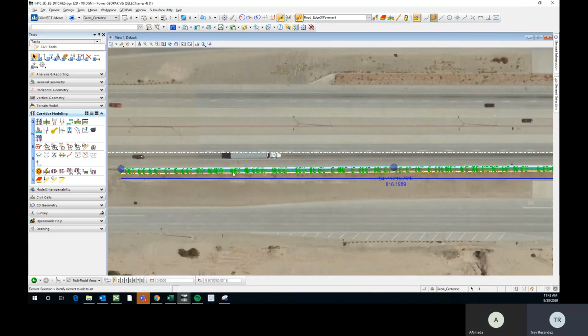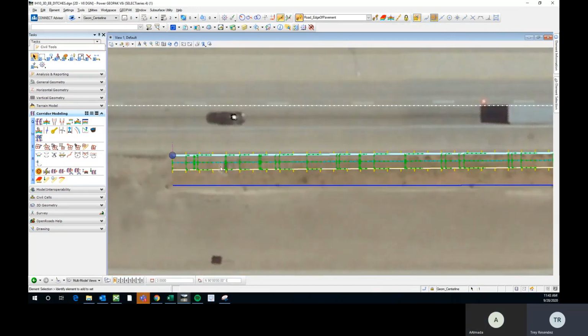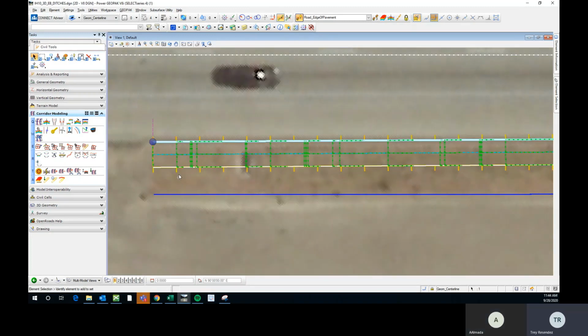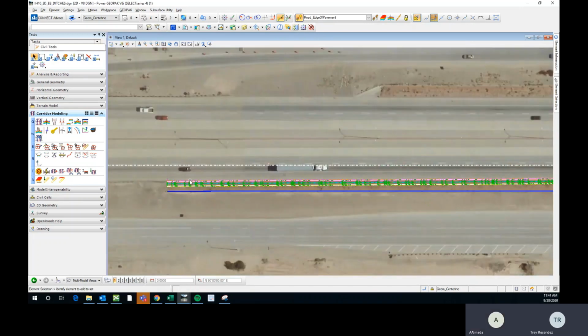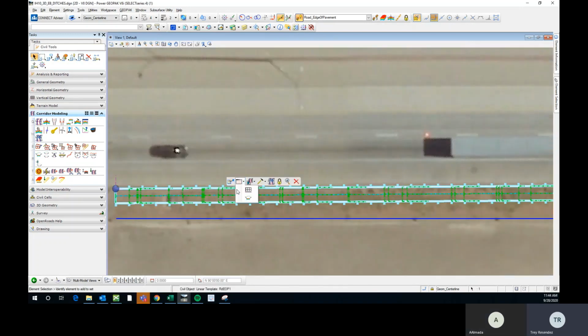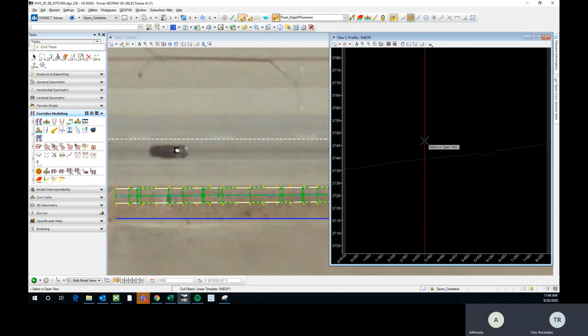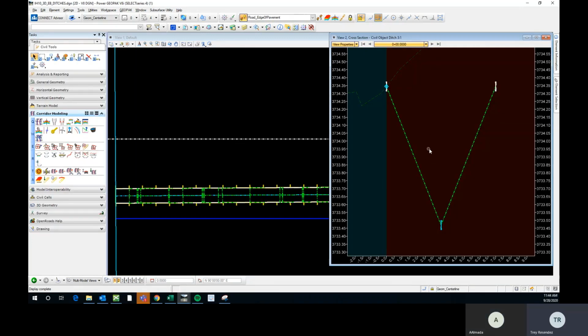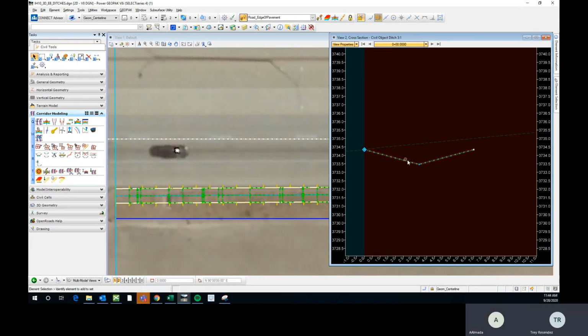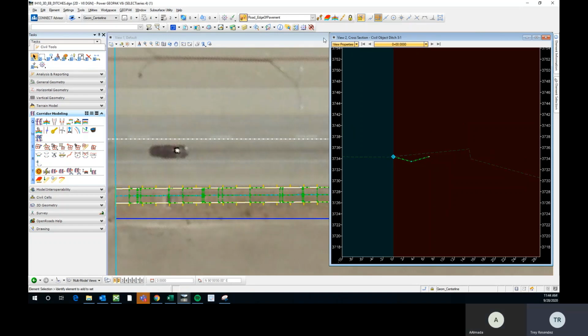So now you see that we have our little section, but it's not following our other hinge, right? If we look at the typical section, the dynamic cross sections, you can click on the linear template and then go to the second little icon, and then come to open cross section model. Pick another view, click inside the view, and then we can see the dynamic cross sections. Okay.